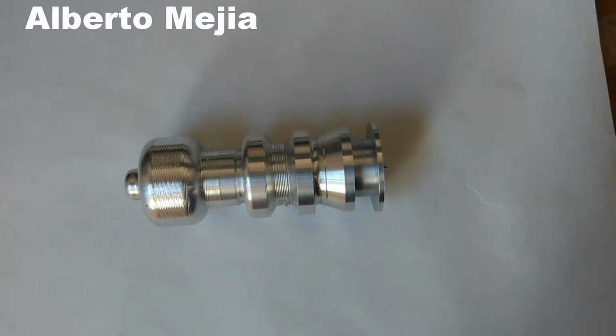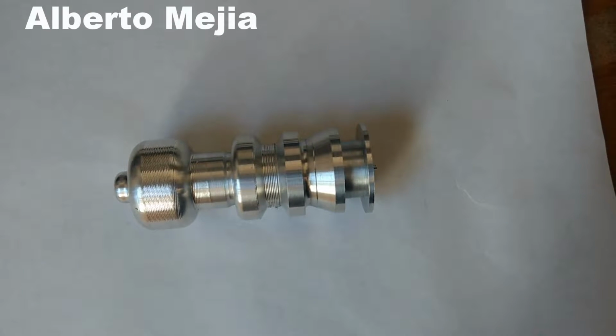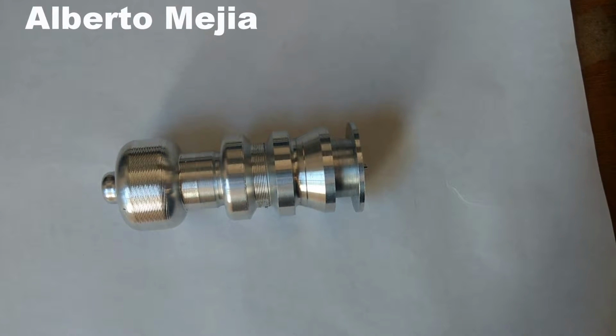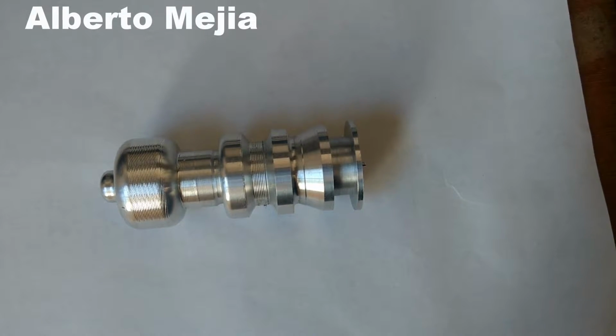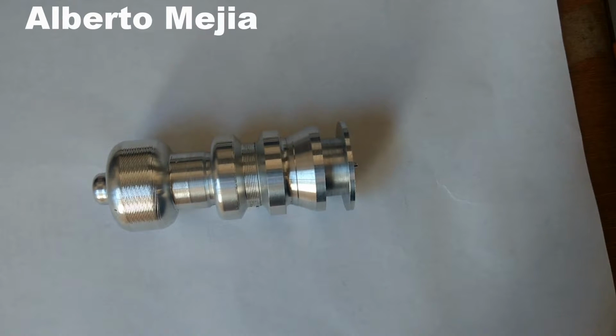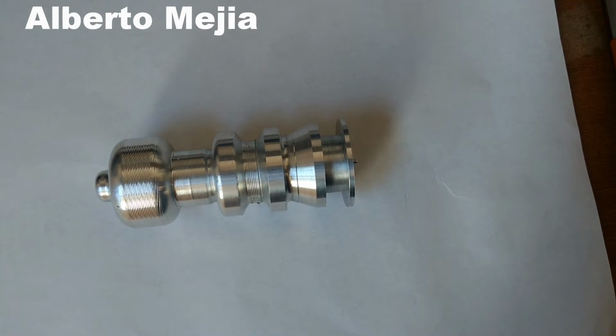We can see at the end of the process we got our finished part. We got one problem. The finishing tool was having some trouble doing its job because the bar was too long and we didn't use a counterpoint. The vibration is the reason the finishing process is not that good. The vibration was caused by the rotation of the spindle and the finishing tool pressure going into the part. That's why in some areas the finish is not that smooth.